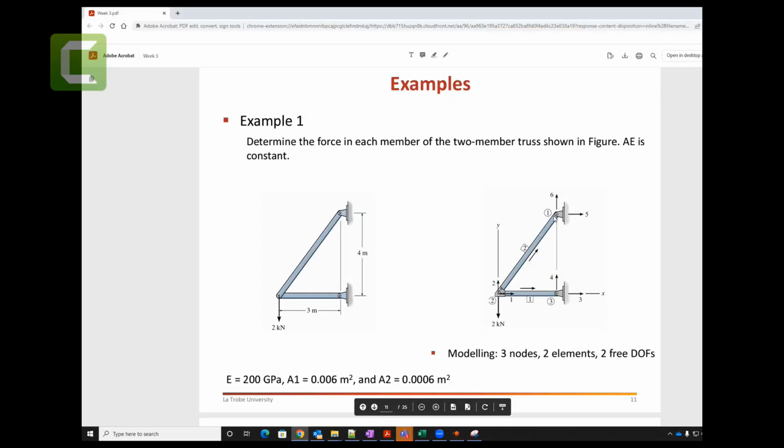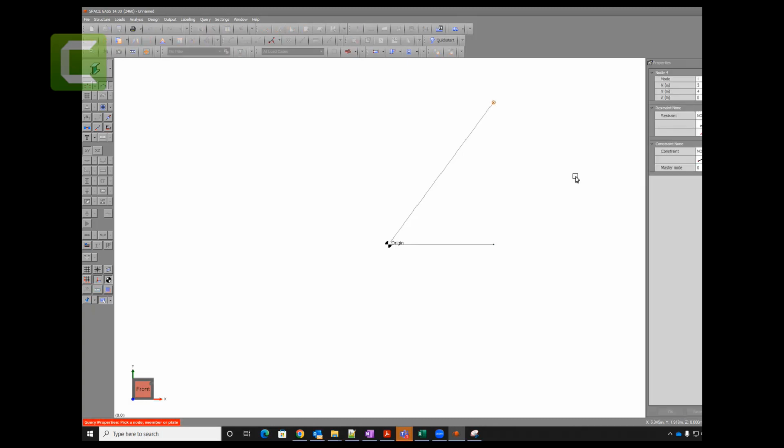Here you have a pin support at here and you have a pin support at here. So in here, does everyone agree with me? When you go close to this point, it will just come back to the green round. Click on here, single click or just escape, just double click. When you have highlighted green, double click. You have different restraints. Restraint means boundary conditions. It has no restraint at the moment. It is fixed. Let me explain those letters.